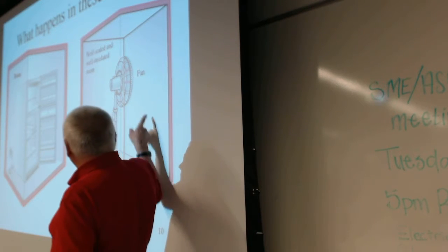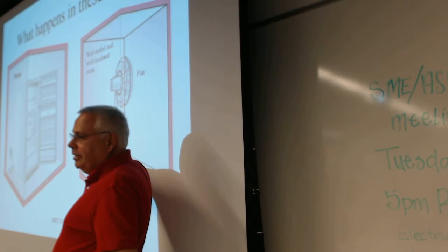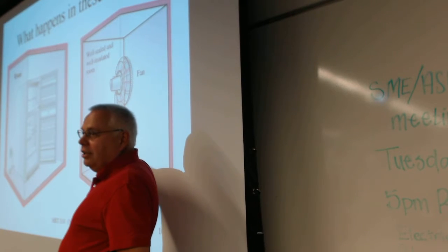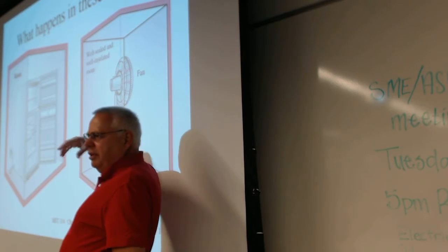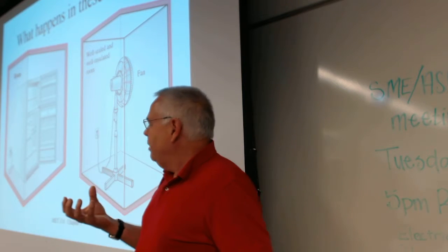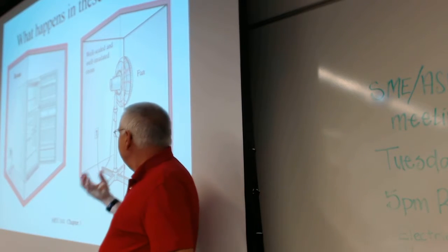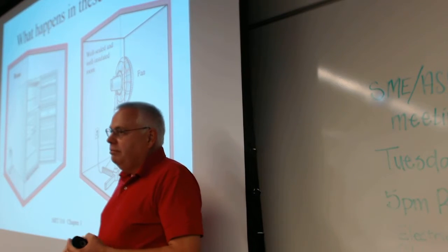Again, it's completely sealed. All that's coming in is this, nothing's going out, and we've got 100 watts coming in. It's basically like leaving a 100-watt light bulb on. Would leaving a 100-watt light bulb cool down the room? No, it doesn't matter if the 100 watts goes through a light bulb or a fan or a refrigerator, it's going to heat up the room.